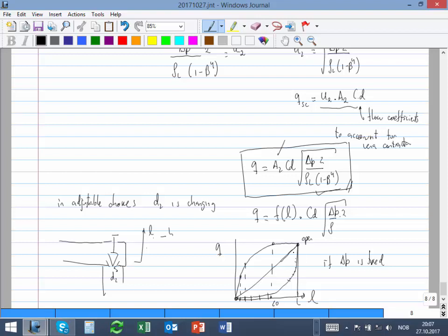So there are different chokes. Which choke do we want? Do we want this choke, or this choke? We want that when we change, it will be really accurate. When we change from 20 to 30 to 40%, we get exactly a big change in pressure drop. So we want a mixture of this choke and of this choke, both built into one. People are still trying to find it, trying to do some magic to make it. But just be aware that depending on the choke that you have, you might have this type or this type. And usually the manufacturer tells you which type of choke you have.